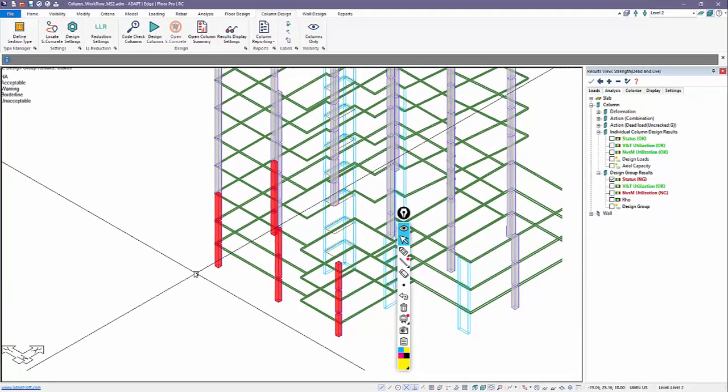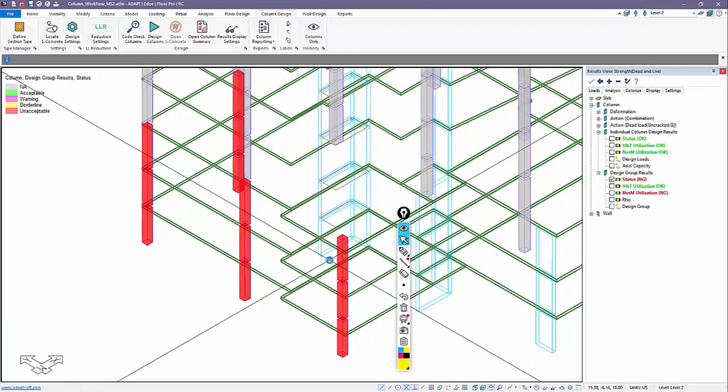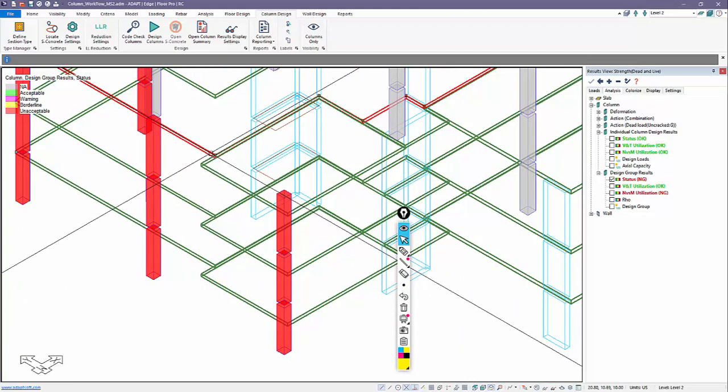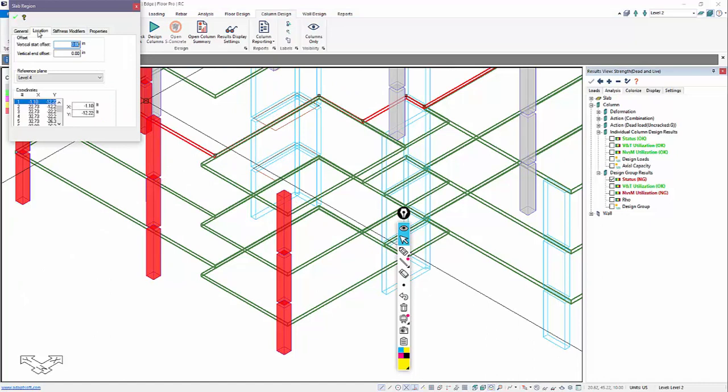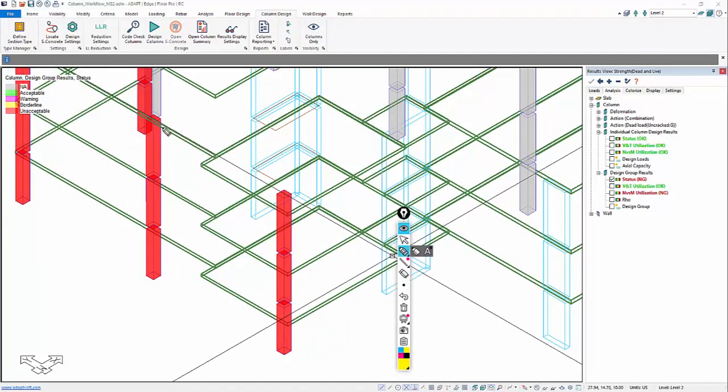Now, if we continue to look at this, we're going to identify why the unbraced length at 360 inches is actually coming into play. And we're going to focus on this stack here. We can see that we have a 7-inch slab, and it's offset by 0. And notice that this slab is actually abutted against this slab. So we have slab 1 and slab 2, and that kind of repeats itself all the way down.